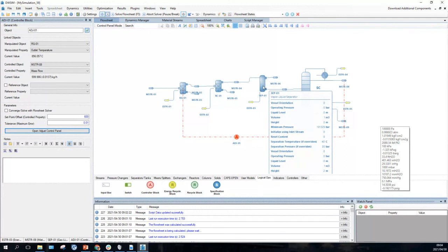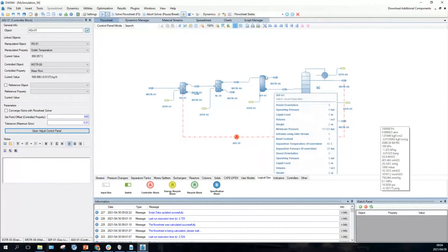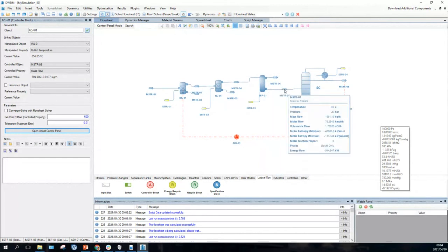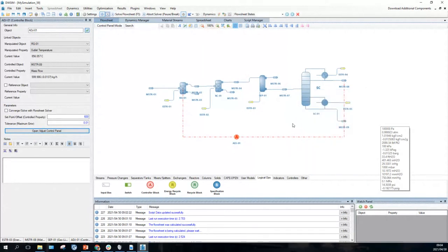Heuristic number 10, I think, says if you've got a mixture of vapors, you cool them down using cooling water, and then you can separate the vapor stream from the liquid. So we get a liquid, and with a liquid you use distillation or various other methods, and here we are using distillation. But because there were dissolved non-condensable gases, it was important to use a partial condenser over here. So this is what I'm looking for. There's usually a mark allocated for showing a partial condenser. This one doesn't show the partial condenser.